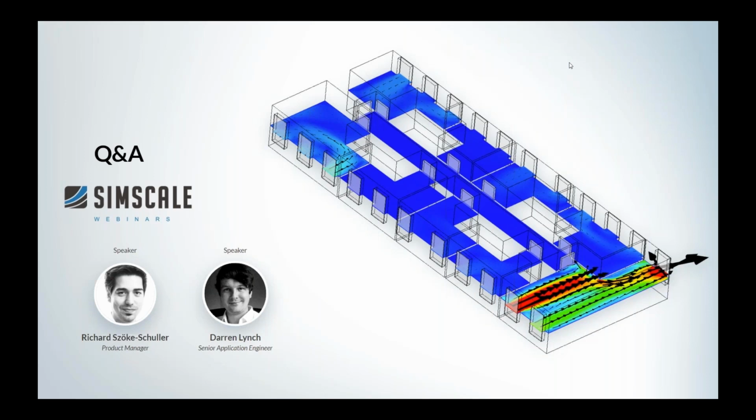and basically also remove locally the areas where we have stagnant air, and also increase the air exchanges locally, which you would need a CFD tool for to really resolve the local effects of the placement of the inlets and outlets of the ventilation system, and together with maybe occupants and other obstructions for the different flow paths through the room.